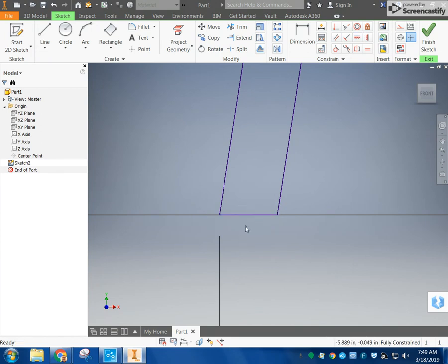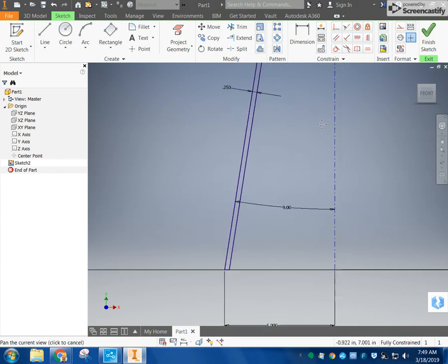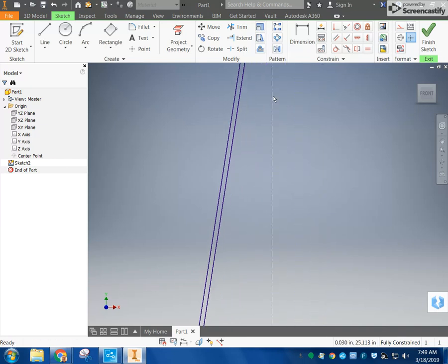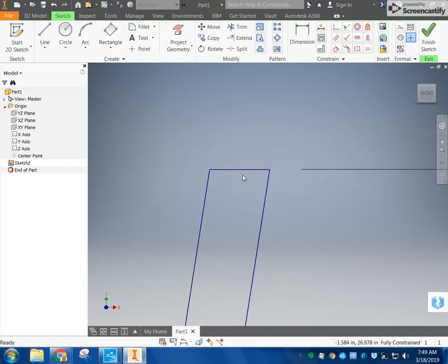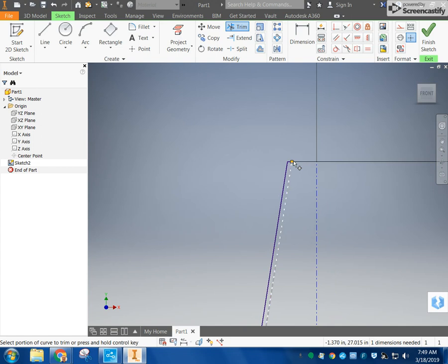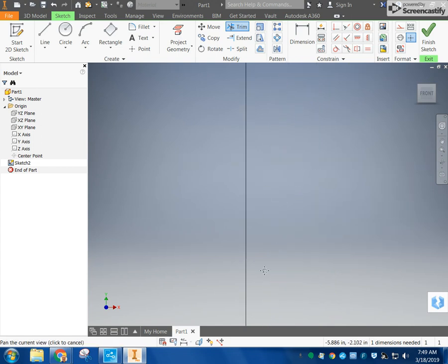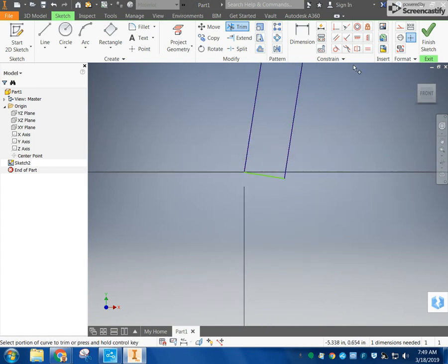And that actually worked out a lot easier than I expected. When I went to do this with a student before, it didn't work so well. But drawing the line, extending it to it, deleting that part in the center and trimming it, let's go back and show that again. So I clicked on this line, deleted it, X is the trim tool, and I trimmed off that part. This last part down here at the bottom,